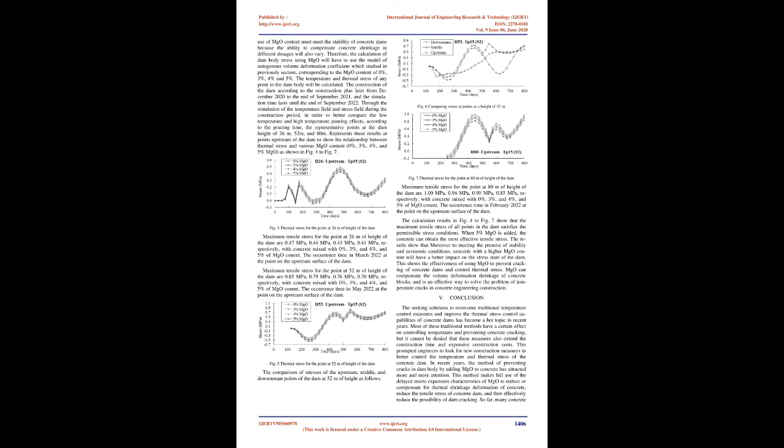However, solving the thermal problems of MgO concrete dams is complicated, and the results of temperature calculations depend on many factors. Therefore, in order to establish a scientific and economical concrete dam construction process, it is necessary to study and understand the influence degree and law of basic factors including MgO about the temperature and thermal stress of concrete arch dams during construction.